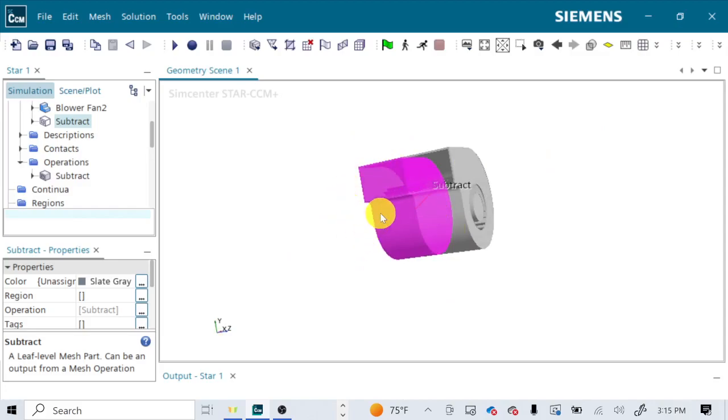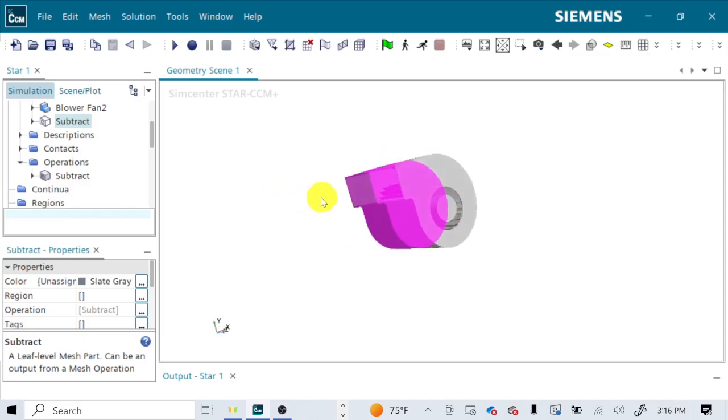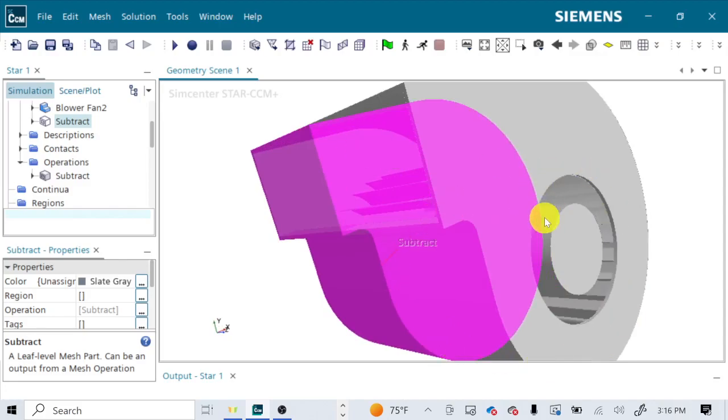But we have 1/2 of our original volume, but this plane is at z equals 0. Remember, that's important because this is going to be a 2D simulation. We could do this in 3 dimensions, but for the sake of sanity, let's not. 2 dimensions, which means this plane will be our simulation plane. It lies on z equals 0 and is parallel to the xy plane. Well, it literally is the xy plane because it's z equals 0.